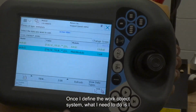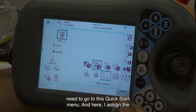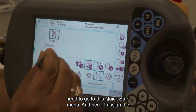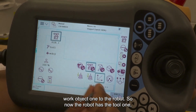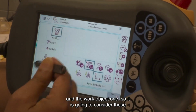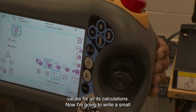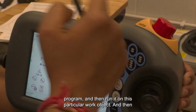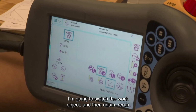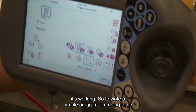Once I define the work object system, what I need to do is go to the quick start menu, and here I assign the work object 1 to the robot. So, now the robot has the tool 1 and the work object 1. So, it is going to consider these values for all its calculations. Now, I am going to write a small program and then run it on this particular work object, and then I am going to switch the work object and rerun the program. Then you will be able to see the difference in how it is working.